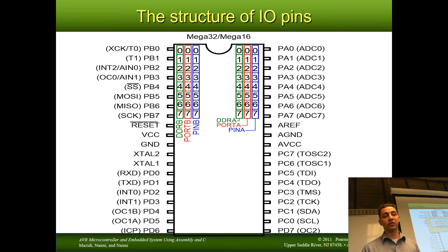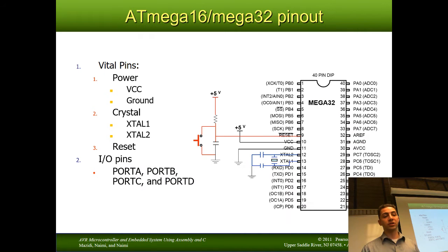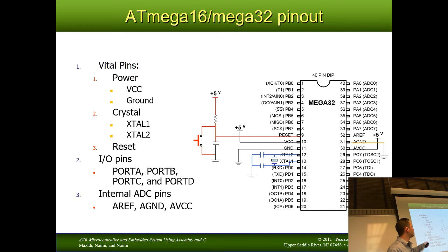If I go back to that original setup here, this is an example of a pull-up resistor. Normally, when this button is unpressed, this reset pin has nowhere to go through the button. Current doesn't flow through the capacitor. So the only way that current can flow is this way, through that resistor. Now, reset is a high impedance input.